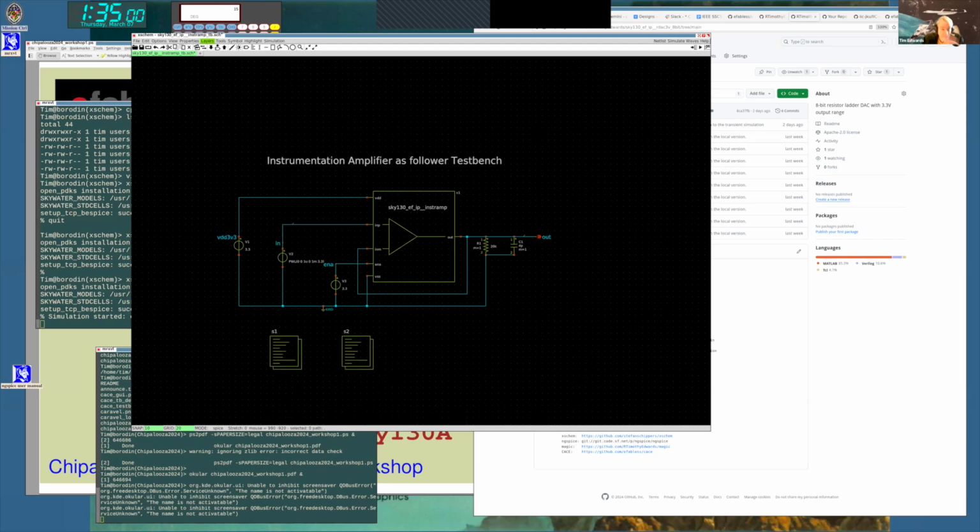And if I do everything manually like this, I would have to do this over and over and over again for different corners, different temperatures, different voltages, and I would have many test benches, or I would be implying that every time I want to do a different simulation, I have to go in and change something manually, save, do a simulation, get results. That's why it's very, very helpful to have a system that does all that automatically for you.